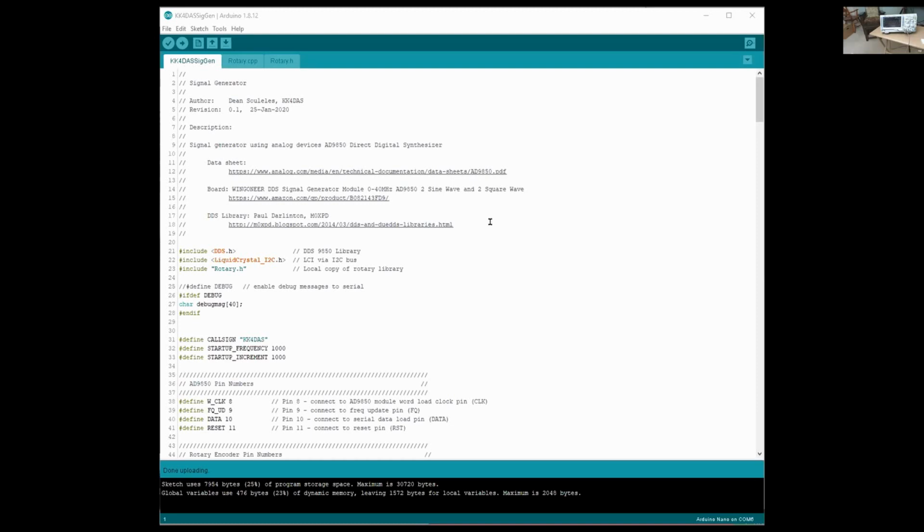It's actually what's made it possible for somebody like me, who is not an electrical engineer and does not have an electronics background of any significance, to build a single sideband transceiver, because the chip that I use, the SI5351, generates the frequencies. The most complicated part of a single sideband transceiver is getting those oscillators at the right frequency and getting them stable. And here, you program it in, and you get a stable signal out.